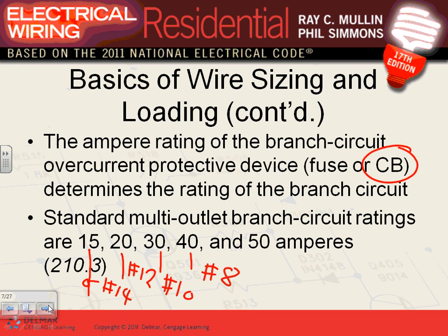So, Phil, my friend, you're going to either be 15 amp, doing 15 amp lighting circuits and convenience receptacles, or you're going to be at 20 amps. By code, you are forced to do 20 amps in certain applications. Kitchen is one of them. Or you're going to be at 30 amp on an air conditioning, or you're going to be a 40 amp. Anybody remember what typically in a house is a 40 amp? Range. A range. So if you write these, you're done with circuiting.